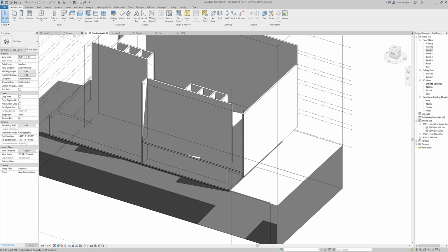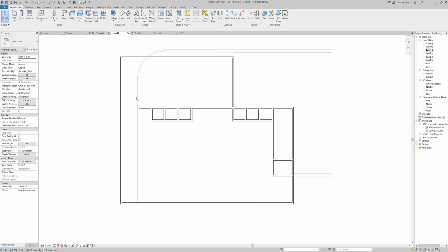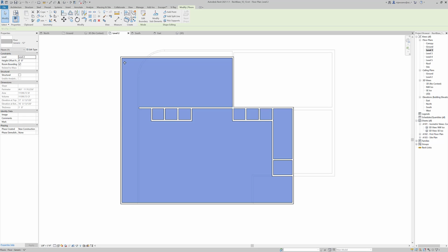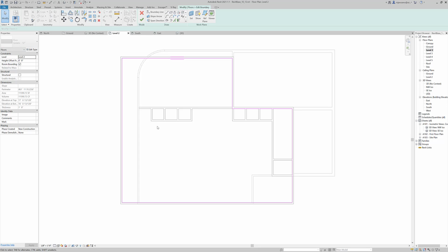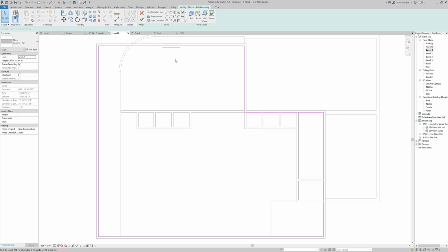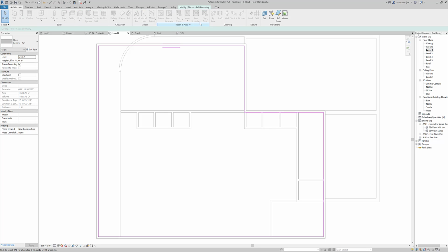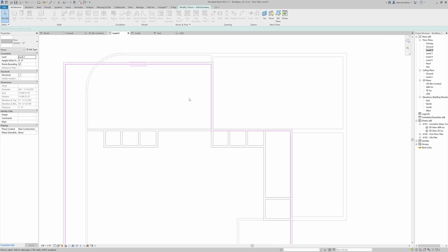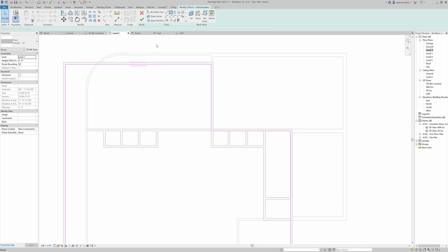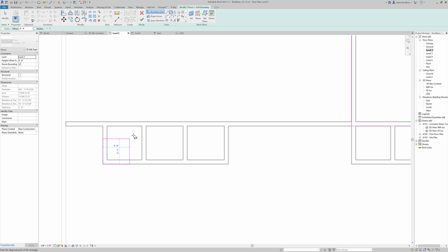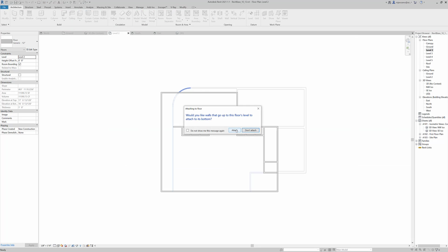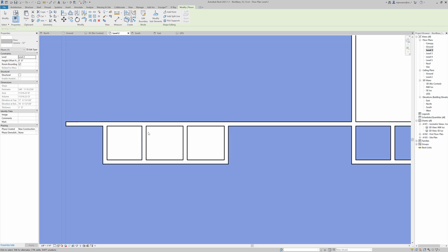Yeah, let's go ahead and go to our level 2, and I'm going to actually click this floor. So here you could see I eventually hit the floor, and I want these to be shafts. There's a couple ways. There is actually a vertical opening tool, or you can go ahead and edit the boundary to cut out this area. And if you have multiple of them together, you can actually sort of do something like this, where you have an opening now.